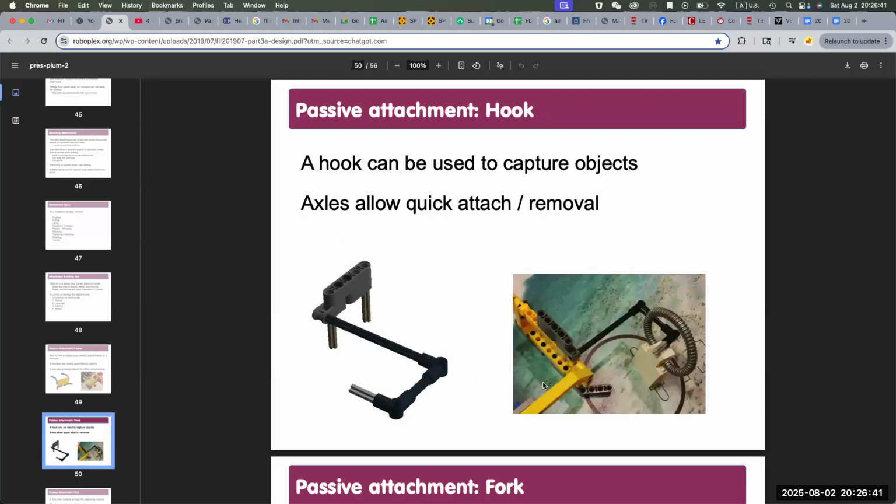And this is a hooker. For example, you can use a lift arm to bring the bag back, or you can use a hooker. Maybe the lift arm can slip off during transportation, right, if you don't have a locking mechanism. But this hooker will make sure it grabs firmly because it actually pushes the object against itself, right? So that it's not going to easily slip.